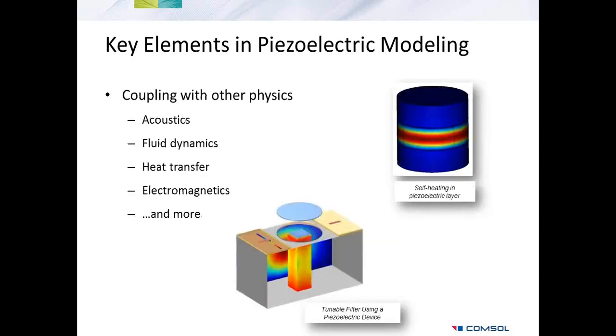And finally, one thing that you definitely need to consider is the effect of additional physics in your analysis. For example, one of the design issues with high-frequency piezo oscillators is self-heating. Self-heating is just a name given to the phenomenon of heating up of a vibrating piezoelectric material due to the structural damping and polarization losses. Such unwanted effects can degrade the performance of the vibrating material. In COMSOL, you can easily combine a piezoelectric simulation with a thermal analysis to quantify the effect of self-heating.